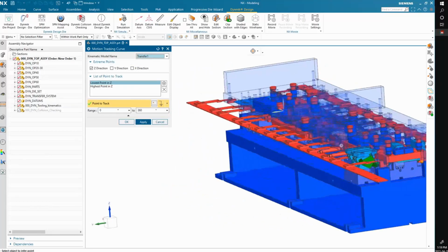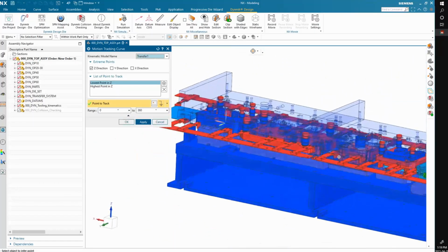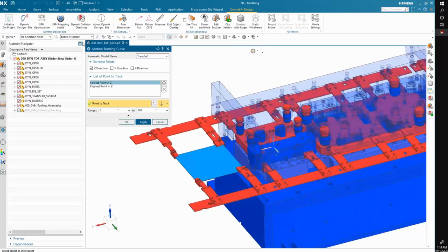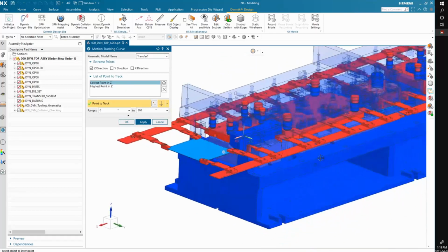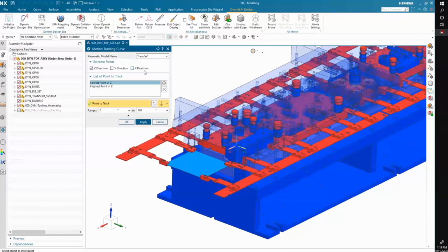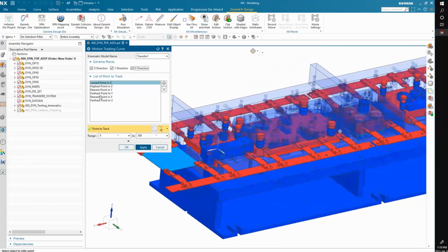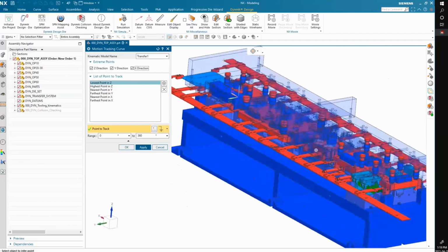When you're using your transfer, you need to know where your transfer's extreme points or any point of your interest would be traveling in terms of this overall operation. For instance, we have the standard directions X, Y, Z, so I can get the highest, lowest points, nearest, farthest points in any direction. Automatically, the system can give you that. Or you can pick your own point.